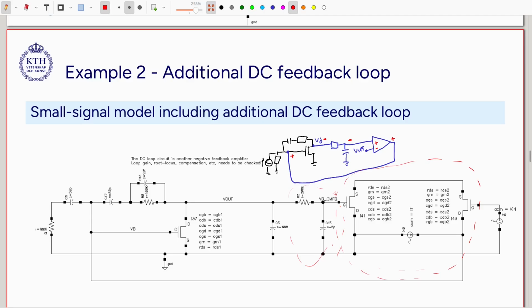And then we tested: if this is minus at the drain, it will be plus. We follow, this is plus, it is converting into minus here, and then the filter doesn't change, it is minus. And this is the plus terminal of the amplifier, so it is correct. It's a negative feedback system, and then we have to do exactly the same things that we did before.